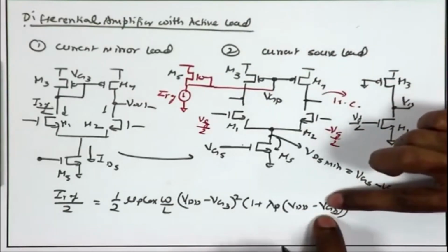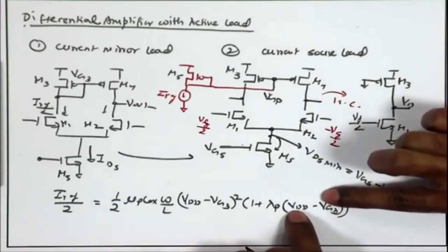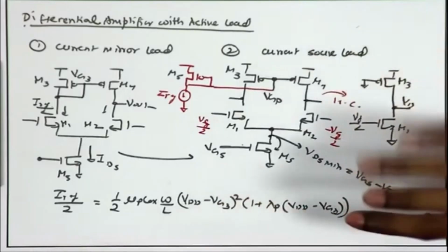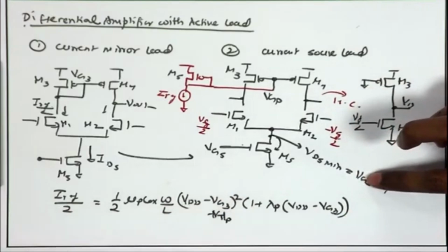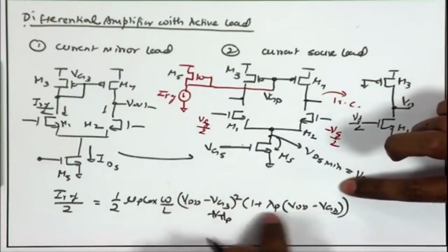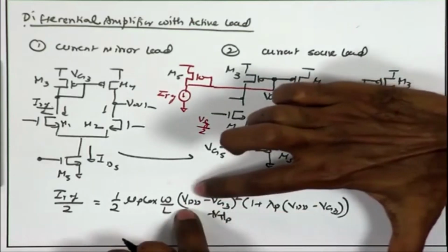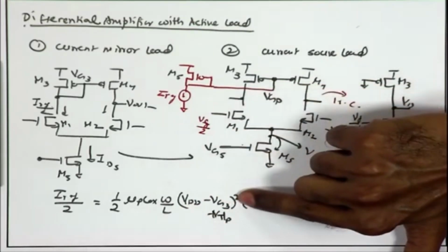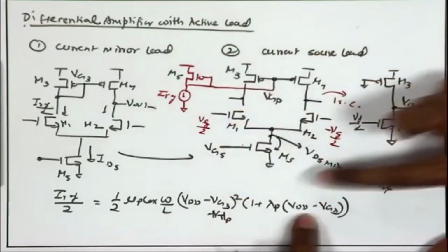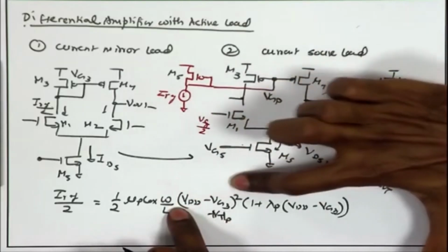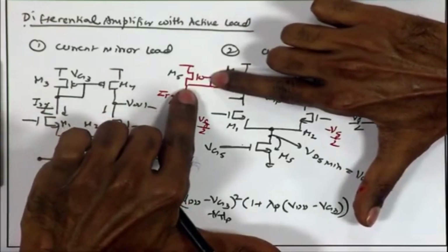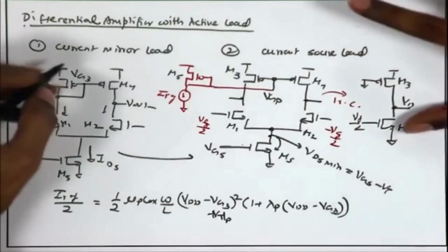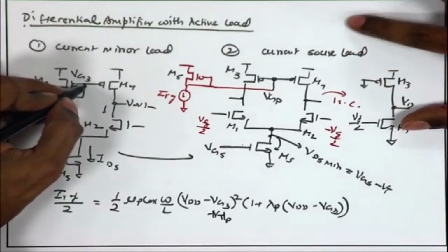and assuming VG3 is going to be few tens or hundreds of millivolt below VDD, or below again another term, mod VTP. So, again the lambda dependency is much weaker, because here you have a much stronger dependency determined by the square term or the quadratic term. So, here the VG3 is not primarily determined by the lambda, rather it is determined by the quadratic term. So, we have a scenario similar to the diode connected branch of the reference current source, and therefore, we do have a relatively well defined VG3.